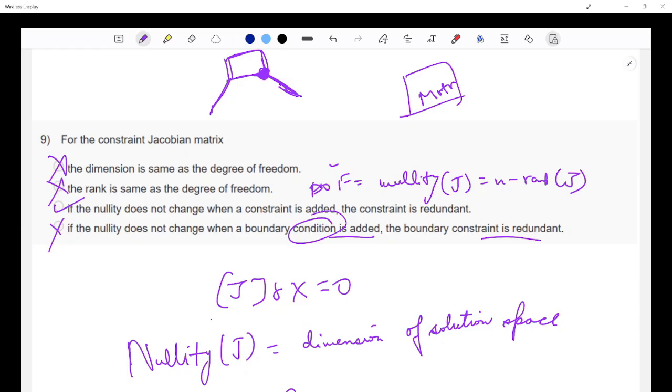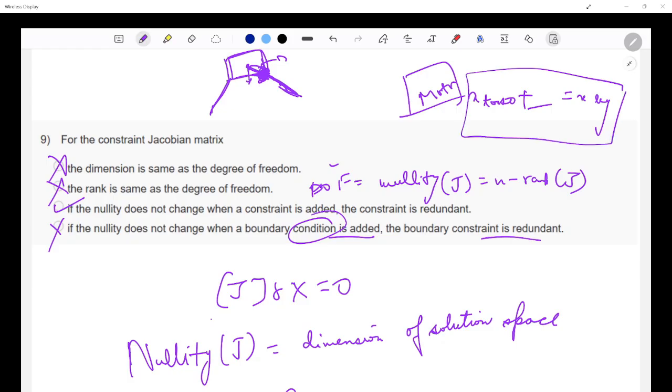Now how would you use this boundary condition? Let's say here it is x, I use a rotation matrix, I come to this point, and for the leg also I have defined some coordinate system, and then I say that x of torso, shifted by plus something, is equal to x of leg. If this is my boundary condition, how am I going to use it in the system? It's going to be through a constraint. I'll bring this term to this side and make it equal to 0, and this would be a constraint to the system. So all boundary conditions are constraints.